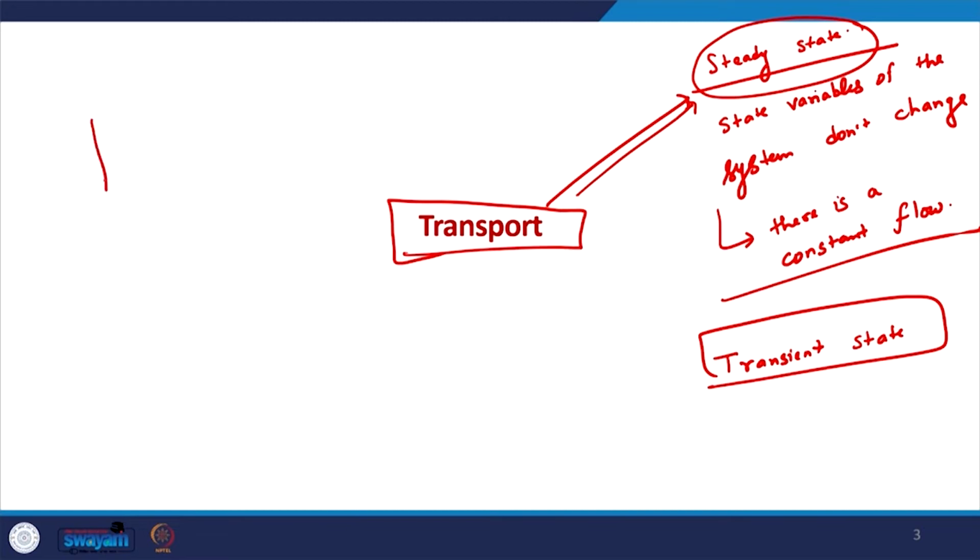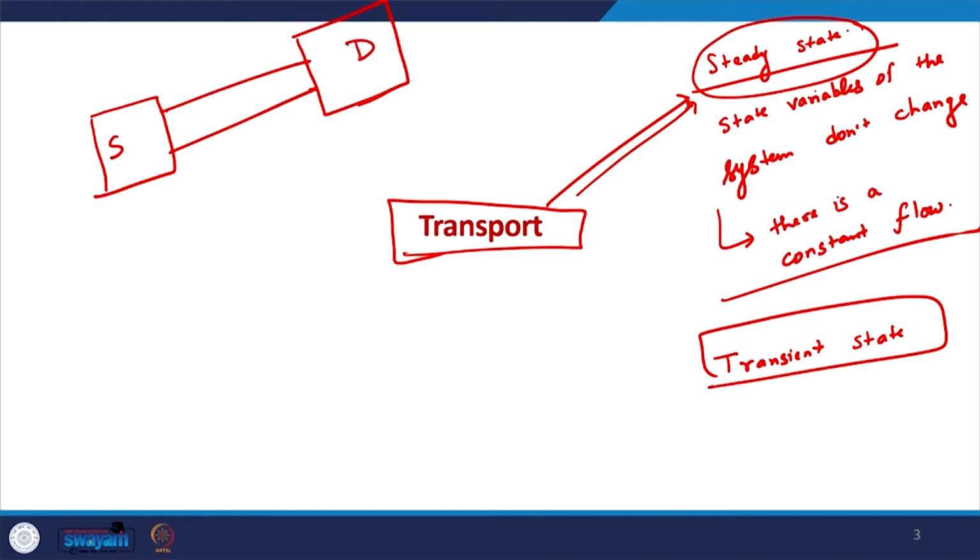So that's why now we need to see if we can use the idea of Fermi function in transport or not. And there is an important approximation that we need to make, and this is not just an approximation, this is very close to the reality that in a practical device, the source and drain regions are generally either metals or heavily doped semiconductors behaving like metals, almost behaving like metals, and these regions are extremely large as compared to the channel region in between.